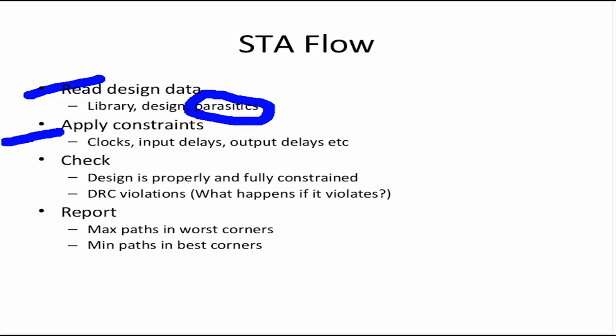We'll see why, because we are talking about post-layout. Some things will change. The nature of clocks will change. So we will see how we modify or add to these constraints and what important things we need to focus on, but know for sure that the constraints here will be slightly more than what we applied in synthesis.